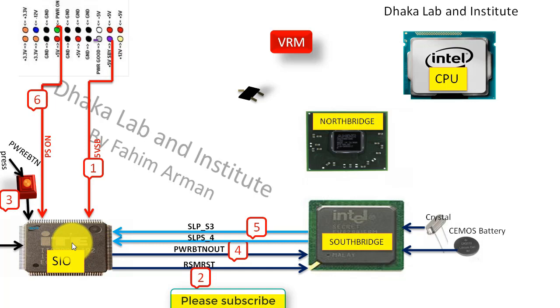Then we can see there is a green wire here, and there will be 5V on it. When the power button is pressed, the voltage on this wire will go low, and the low signal goes into the IO chip, and then all the voltages 3.3V, 5V, 12V will be activated.